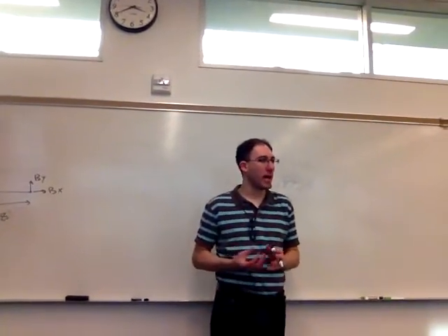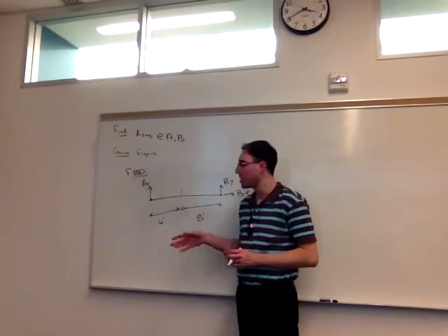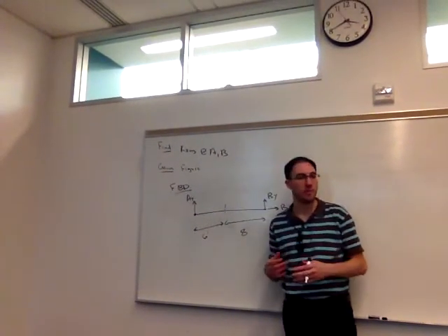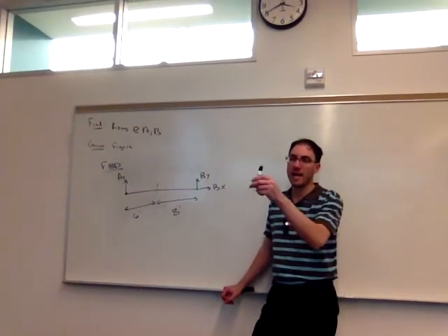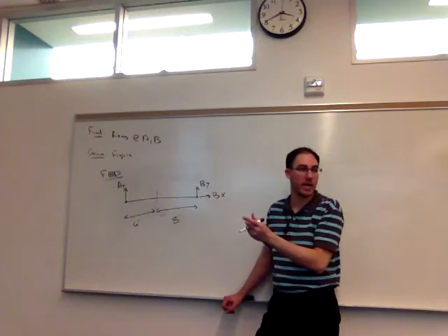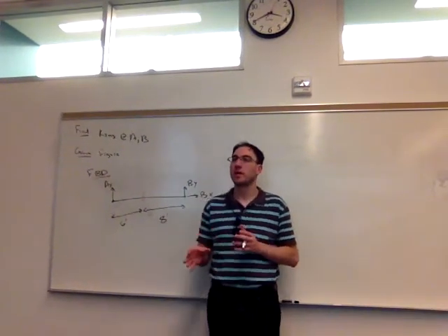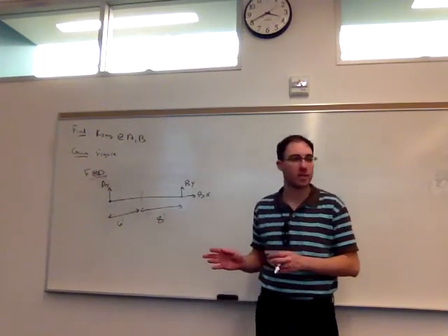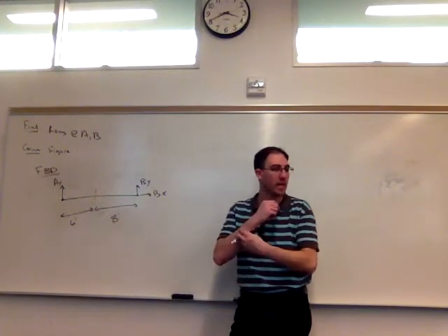I model that the same way. The distributed load I now want to model or simplify to point loads, because those are going to be easier to handle when we get to our sum of forces, sum of moments equations. In this case, I can look at it as a trapezoid from A to B, but I'm going to recommend we break it down into even simpler shapes. Looking at the problem, I have a right triangle that goes from A to 6 feet to the right of A, and then from that point to B, it's just a rectangular load.